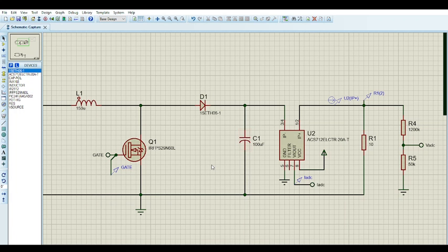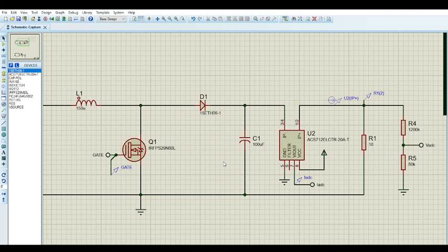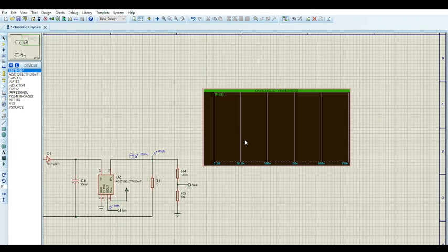if you're dealing with a regular buck, a regular boost, or a flyback or something that does not require too large of a capacitance, where the capacitor you calculate for it is a low one, that is a good thing for control anyway. And you might be thinking, oh, the ripple is going to be ridiculous. No, it will not be ridiculous. It's just the math, it's just the converter. It's going to be fine. So 100 microfarads is more than enough for this particular example anyway, for 100 kilohertz. And yeah, that's one thing I wanted to point out.